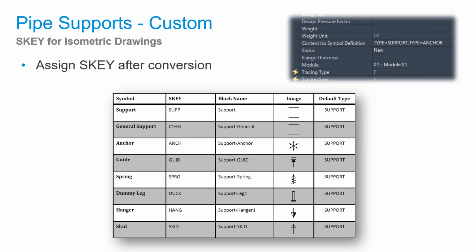So if you were going to create a collection or a catalog of parts, you would maybe want to take those and copy them across the drawing and scale them up across the size range you're using. And then you could do plant part convert on each one of those, add the single port that's needed there, and then when you take those into catalog editor, you could import that group in and have basically built a part family of sizes needed for those supports.